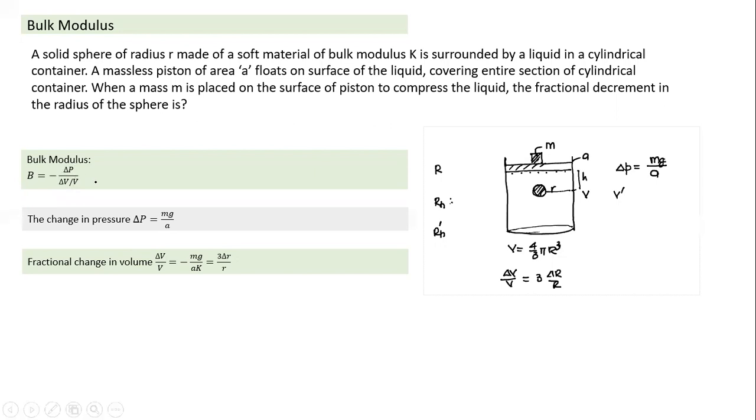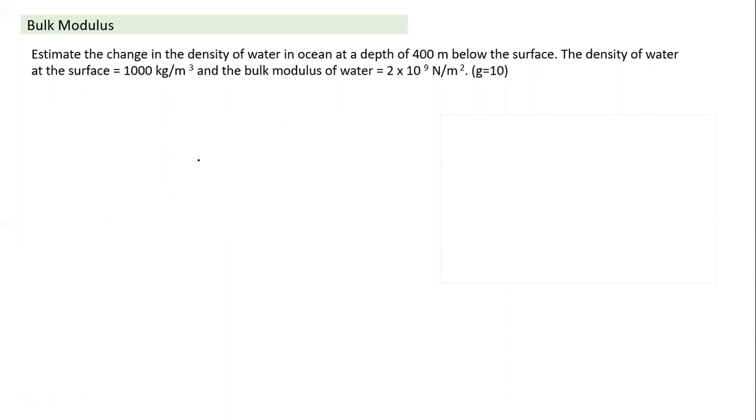And change in pressure is delta P and change in volume is delta V. Okay. And one more question here. We always say liquid is incompressible, hence its density will not change. But now we are talking about how everything is compressible. If everything is compressible, everything has some finite bulk modulus. So yes, volume will change and hence the density will change.